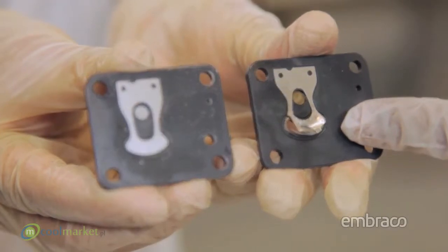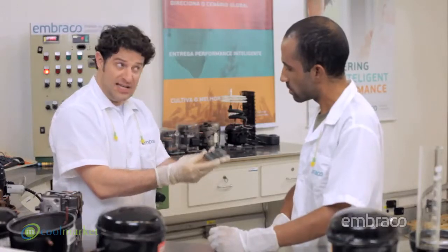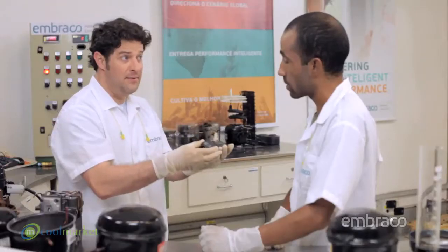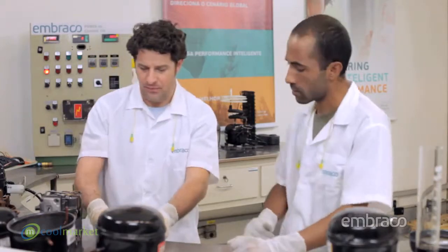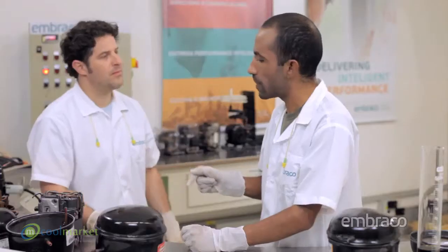And this damaged valve plate, is it related to excess gas charge? That's it! This warping or breakage may be related to excess gas charge, and in some more severe cases, the valve can break. But it might also be the incorrect compressor used. For example, a low back pressure compressor, LBP, being used in the system for medium or high back pressure, MHBP. Oh, for this reason, it's important to always use the suitable compressor for each system.